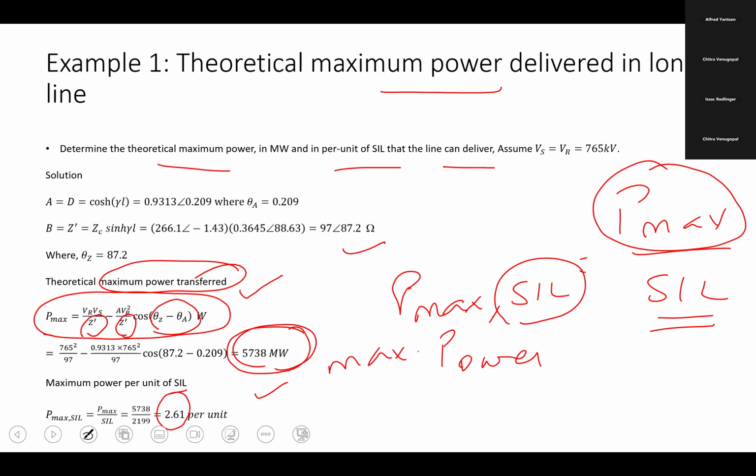So the maximum steady state power, that's like the ceiling of the line. Yes, that's the ceiling. Usually, theoretically speaking, for understanding, what you said is correct. But usually, fault is not calculated based on the power; it's calculated based on the current and voltage, separate entities.